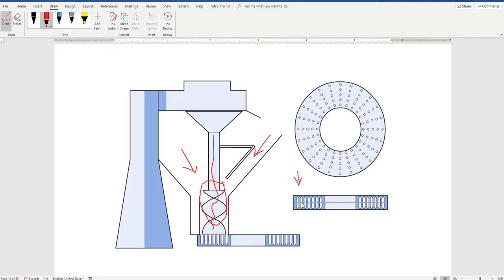When the capsules are rectified and they get to the two ring system, separation will be done. Now the process of separation, to separate the upper ring containing the cap from the lower ring containing the bodies, this operation is done manually. That's why we don't call it automatic, we call it semi-automatic. Rectification is automatic. Separation of the two rings is done manually.